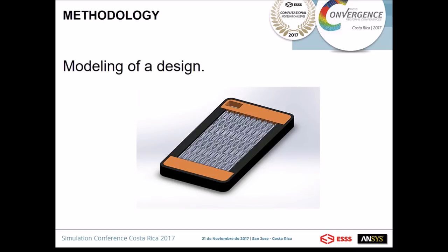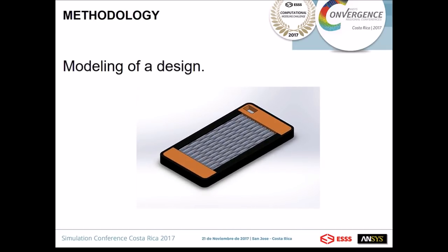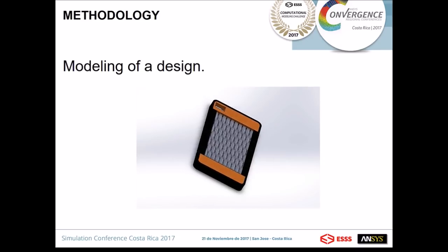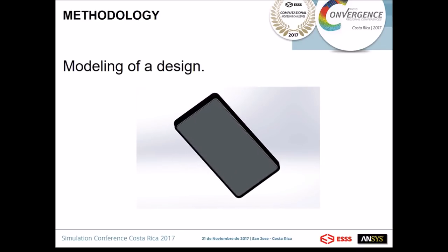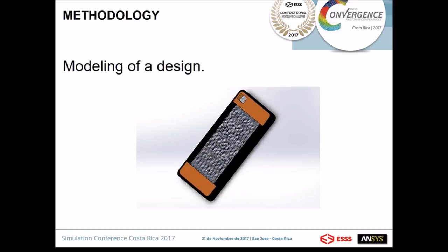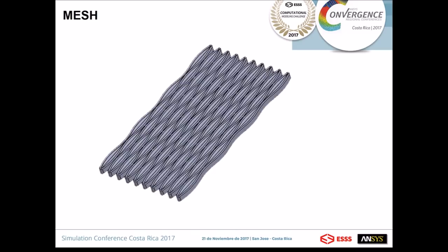For the resolution of our problem, the first step was the modeling of a design using a CAD software to use as base for the ANSYS workbench simulation. An essential part of the design is the mesh, which consists of consecutive arches to create a geometrical shape capable of deforming in a predictable manner. These arches form a supporting structure for dozens of covering lids positioned precisely to allow their deformation in conjunction with the main mesh, making them open pathways for air.